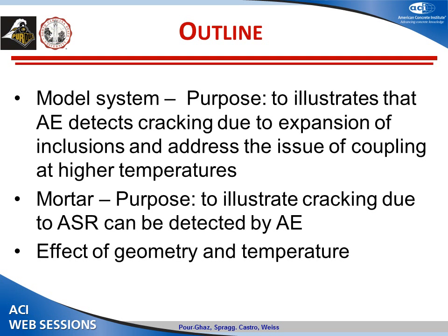Now, this is the outline of this presentation. I will go through 3 parts here. First, I will introduce the concept of a model system, just to take a look at the acoustic emission and whether we can detect cracking due to aggregate expansion. The purpose of that, of course, is to show that we can use acoustic emission to detect cracking due to expansion and address a couple of the issues that we might have by using acoustic emission, for example, having coupling between sensors and sample.